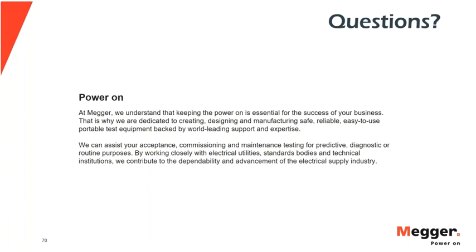There are so many things on this question talking about life expectancy that it might be in good condition right now, and tomorrow you have a true fault shaking the windings internally on your transformer, damaging the insulation, and that'll be the end of it. There's different ways to approach the life expectancy question, right? There's ways to look into sometimes maybe furanic compounds. There's new methanol analysis.